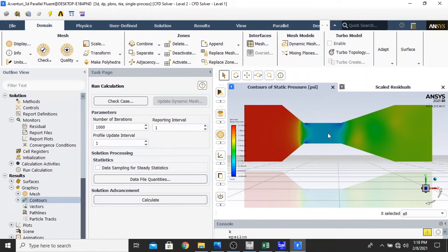It indicates that the pressure value is decreasing, and then after it comes out into the diverging part, it changes to green, light green or yellow colors. It turns yellow. So it indicates that the pressure is increasing again, but the value is less than in the converging part, which has the highest value of the pressure. That is the indication that the throat, the sudden change of the surface area, is contributing to decreasing the pressure.